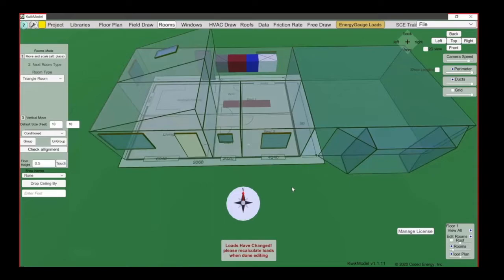And if you go into Manual J, which is where all the calculations are coming from, and you look at the tables, look at the table for the windows, for the heat transfer multipliers for cooling, and you just look at a window and look how dramatically those numbers change. They double and triple and quadruple just as you go from east, west, north, south, and across the table like that. So that really illustrates how big of an impact it has, okay?